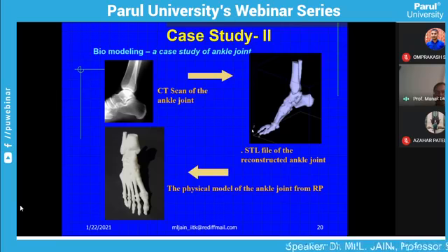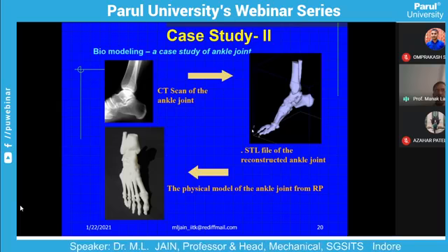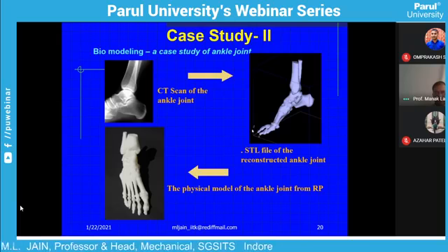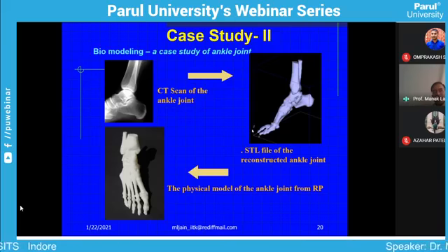So they have developed a common format which is known as stereolithography file format, and all software, whether CATIA is there, whether Unigraphics is there, whether Creo is there, they all successfully develop an STL file. So you prepare the manufacturing file and send it to the 3D printer and instruct it that you go on developing a 3D print form of this particular file.